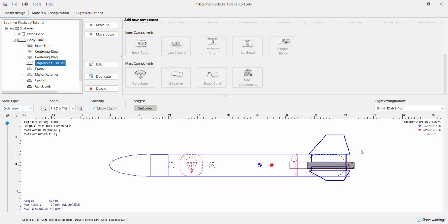First, an unstable rocket in flight will tumble and crash. It could potentially hurt someone, and you will also fail your certification attempt. So we want to aim for a stable design. For a stable rocket, we're aiming for 7% stability. When you look over here at the stability number, 7% will be a stable design. You can do that by changing your nose cone and fin parameters.